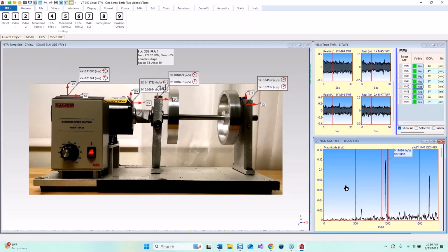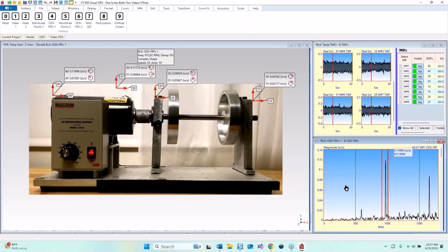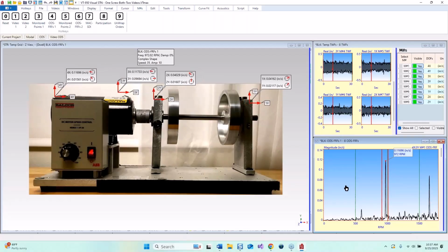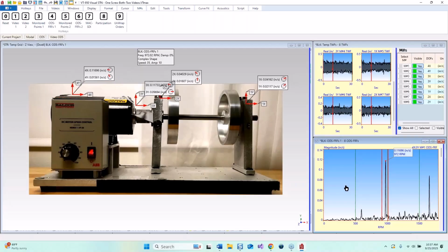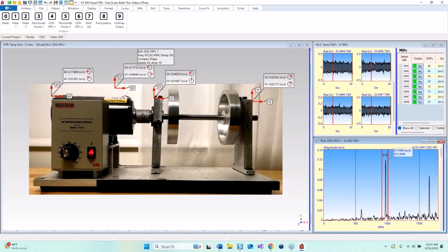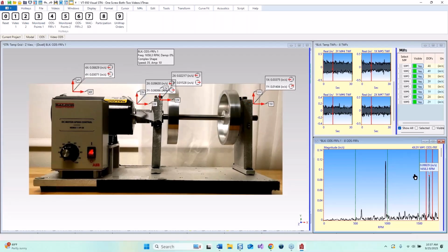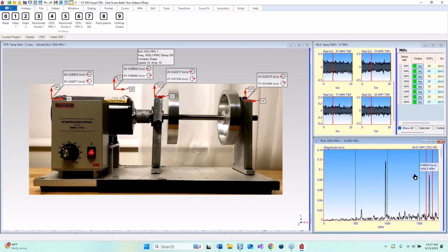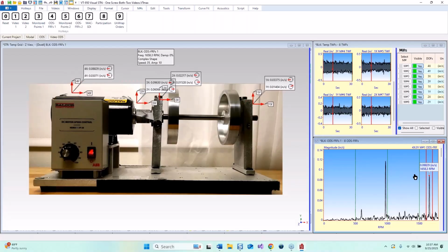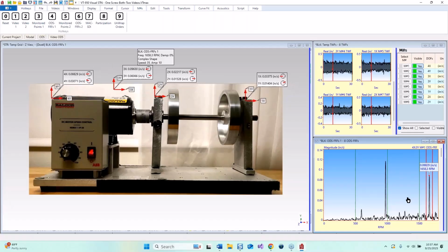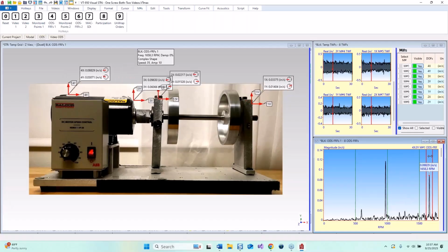And now if I subtract that from 1800, because it wrapped around the 1800, I get 1656. There it is. Well, it's 1658. It's off by a delta F, one sample. So that is the second order of the machine wrapped around 1800.